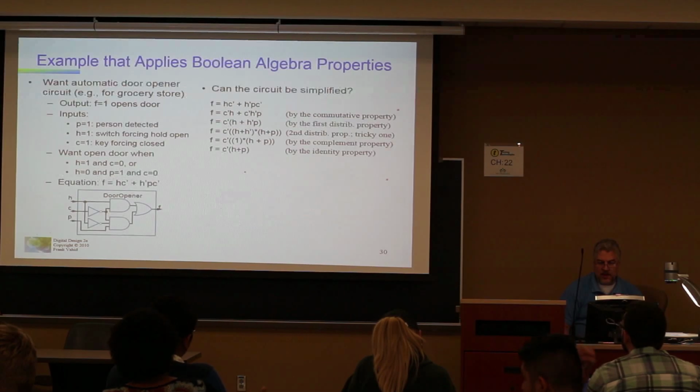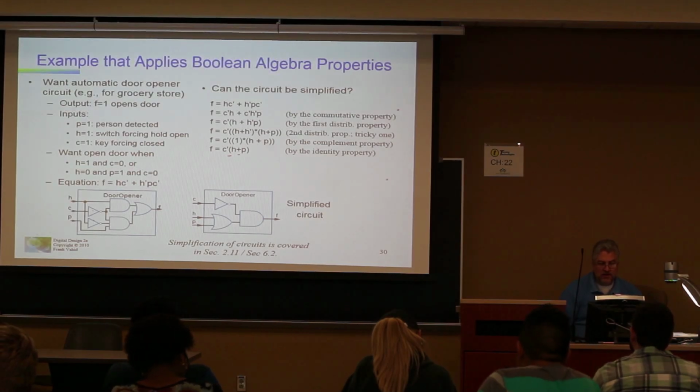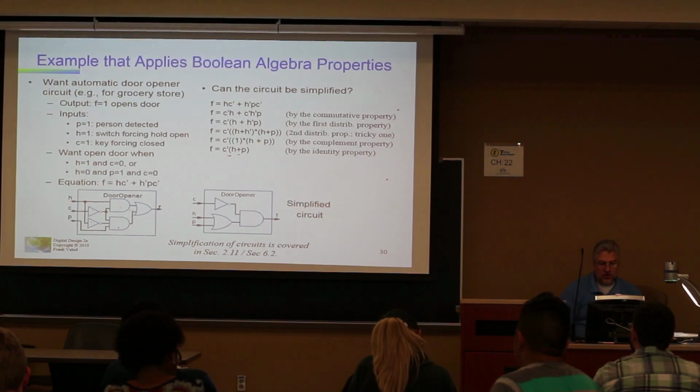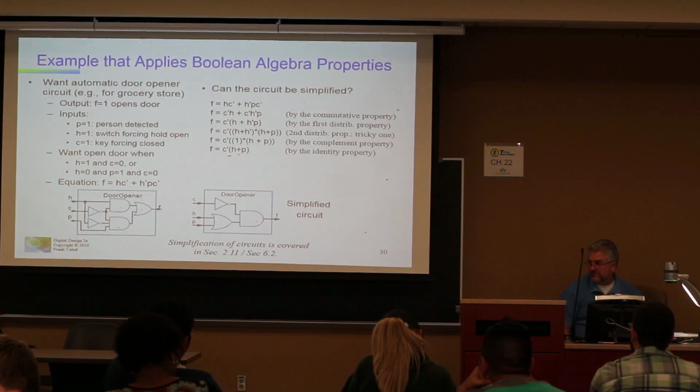If you look at it, it's just 2 gates, right? It's this OR gate, and this AND gate. And oh yeah, there's going to be a prime, so there's going to be a NOT gate needed for that. So what did we do? We went from 1, 2, 3, 4, 5 gates down to 1, 2, 3 gates.